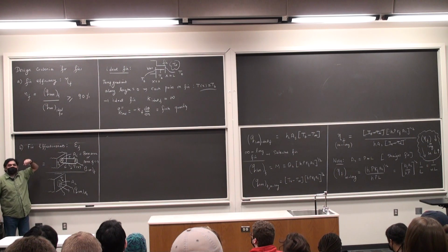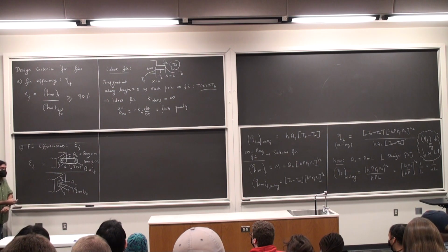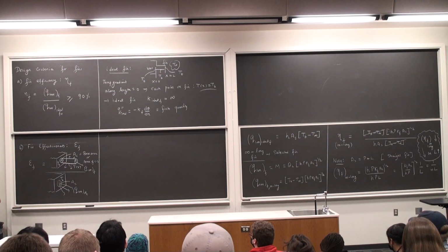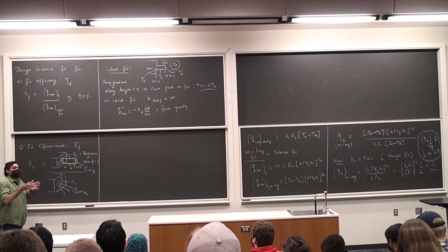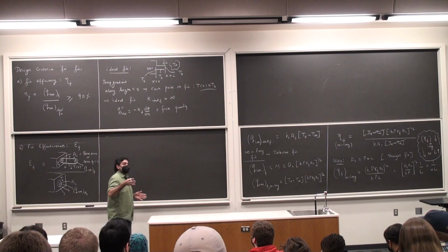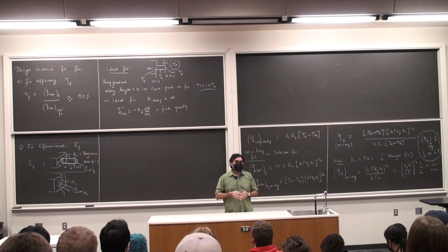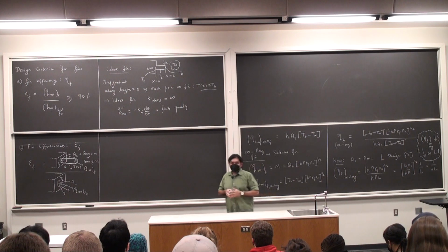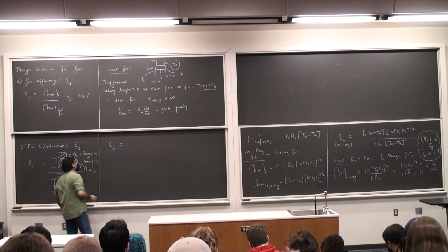The one on the top has to be larger, right? Obviously. Otherwise, what's the point in having a fin? It's just an ornament. And so from that perspective, I compare these two values, and that tells me the effectiveness of the fin, which is a number that has to be at least larger than 2, typically. Okay, these are industry numbers, not something that I cooked up. Epsilon F.